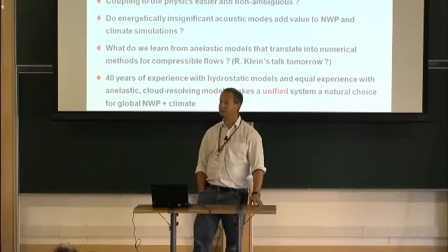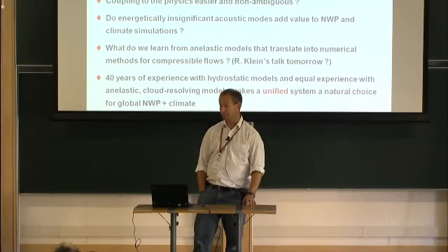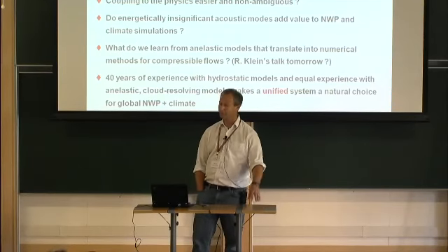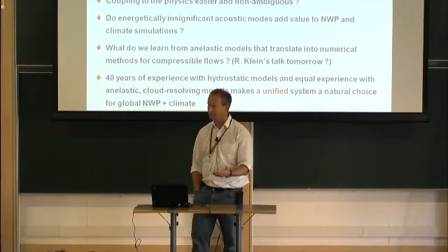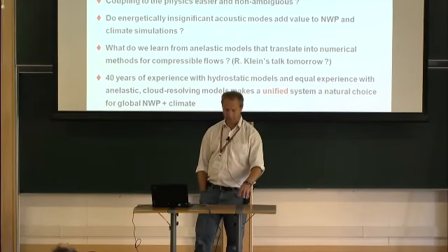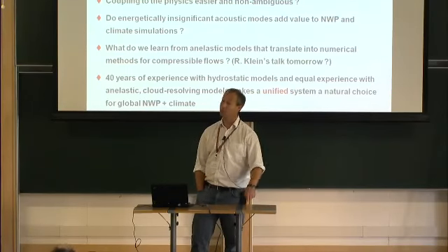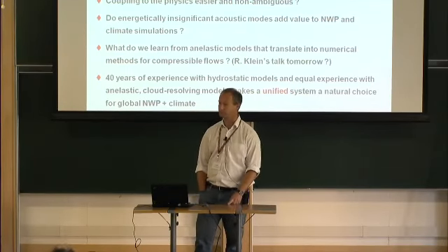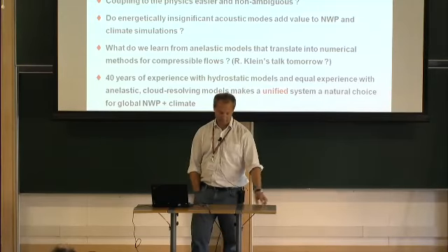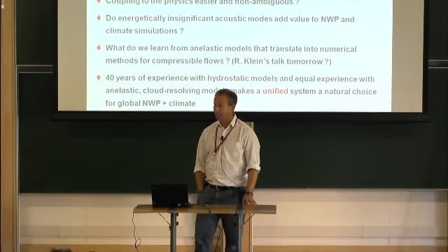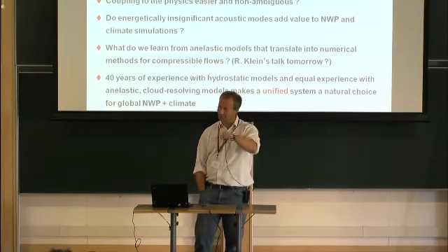No. I started with the Euler equations, basically. I started with the Euler equations, and the transform into this Laplace coordinate, if you like, was done starting from the Euler equation and the z coordinate. The only change I then introduce is this approximation to the continuity equation that I say, instead of 1 over rho d rho dt equals divergence, I say 1 over rho qs d rho qs dt equals divergence. So in fact, I've derived the full equation without throwing anything away. And then you have them all, and then you start to remove the gamma brackets.